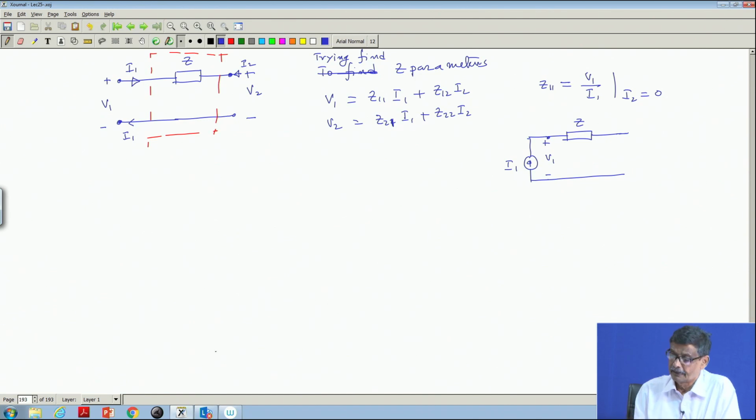to get Z 11. Now, here is the trouble: you can easily see a current source, and here is an open circuit. So, what will be this voltage? A current source, as you know, always tries to force current. Impedance between these 2 points is infinity, because of open circuit. So, this voltage will be infinity, and also this voltage V 1, because this voltage plus this voltage, this will be finite I Z, no doubt, but this is infinite, this will make V 1 also infinite.